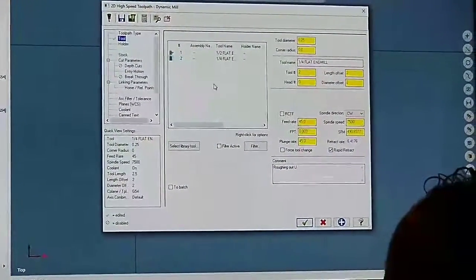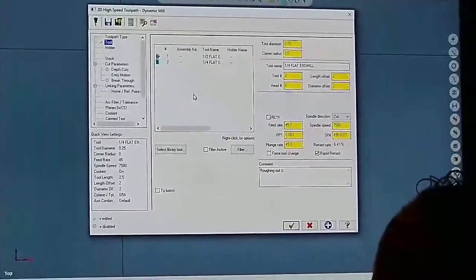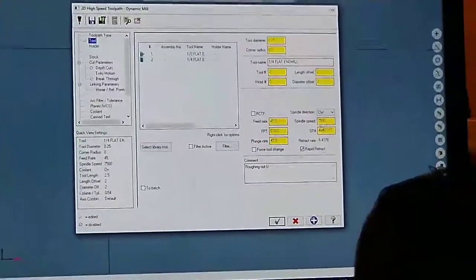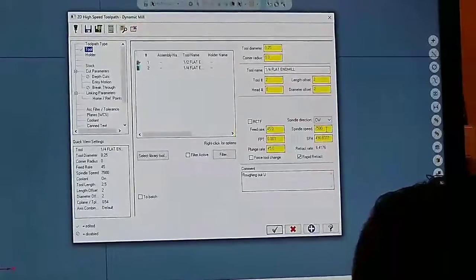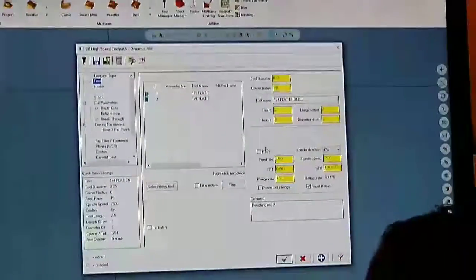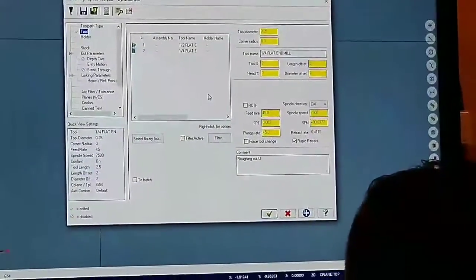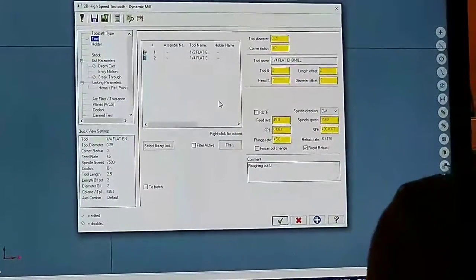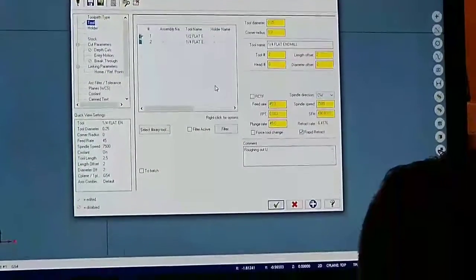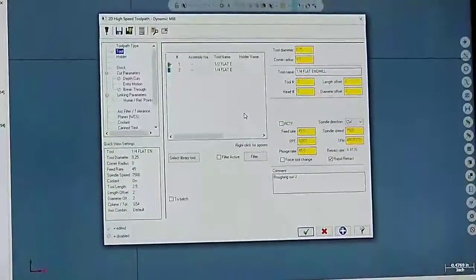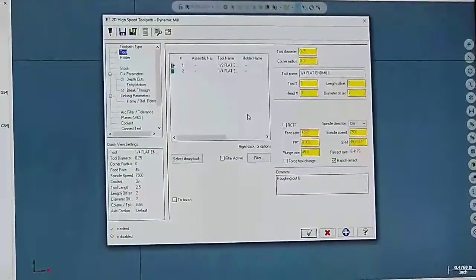But it's still too fast. It's still too fast at 7,000 RPM for the end mill. It'll work. We're still roughing. We're still in a roughing pattern right now. So it'll work. It'll cut that out of there. I guarantee it'll work.